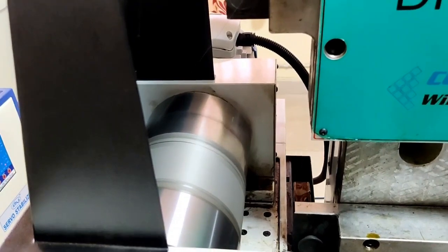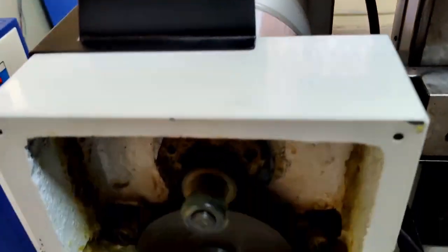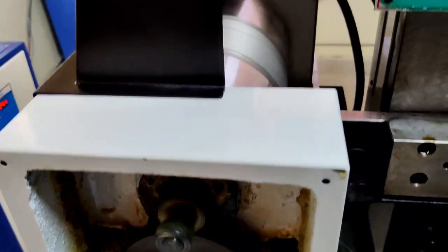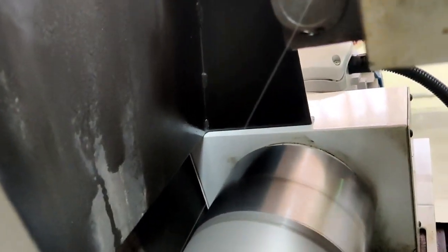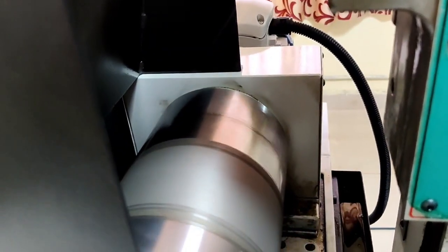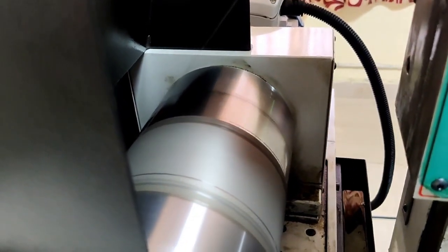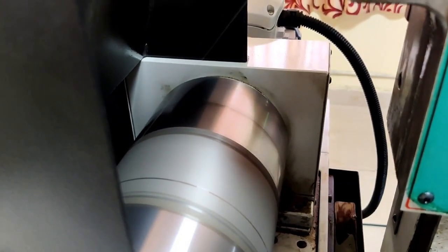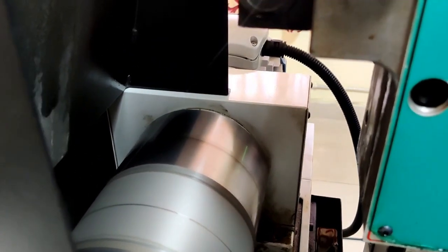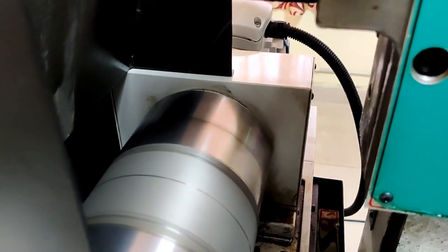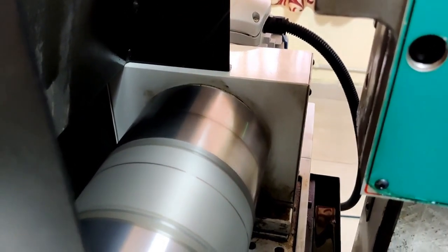In this wire cut EDM, the wire is the tool electrode, and the wire will act as a tool. This wire is wound on a drum, and it is reusable. This is the drum. The wire is fed from the drum and moved in the forward and backward directions, and by using this forward and backward movement, the wire is reused. The wire should be replaced once in 15 days.